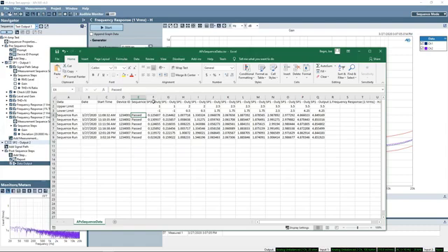and then for every measurement that has a meter result, we get the name of the signal path and measurement and the channel, the upper limit and lower limit, and then for each run of the sequence, the measurement of that meter result. So this is a very nice way of logging the meter results as the project progresses and as you run multiple items. You can look at an entire day's or an entire week's worth of production using a spreadsheet like this.